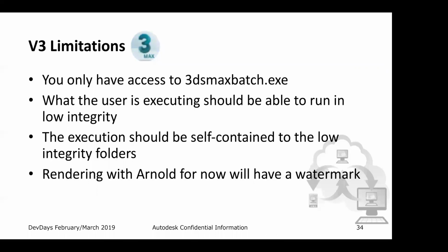Finally, on 3ds Max, we only have access to 3dsmaxbatch.exe. That's the same one we have on desktop to test, and that's the one we have on Design Automation. The user will run on low integrity, so that's important as well for your processes. And you can only run in the executing folder and subfolders. Also, rendering with Arnold for now will show a watermark on those renderings.